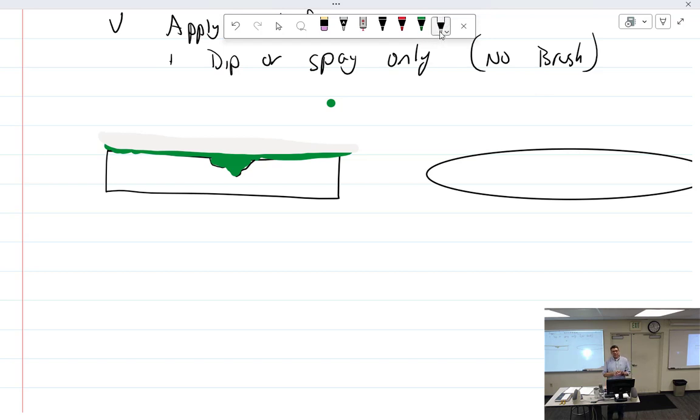And this is the tricky part, timing that emulsifier. Now, I've never personally used this particular method, but in NDT school, we talked about how the process is actually trial and error. Like, okay, 15 seconds of emulsifier was not enough. 30 was too much. Okay, now try it with 20 seconds. And that's kind of how it was done.